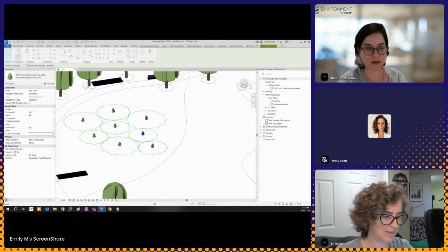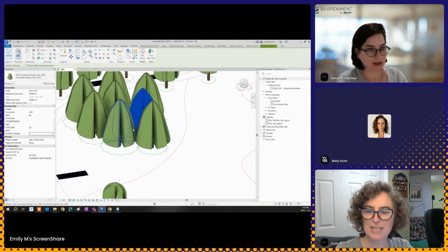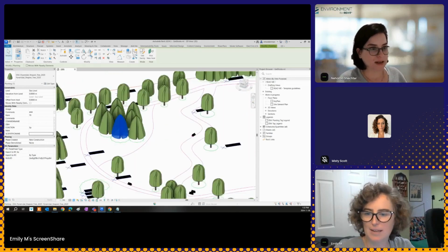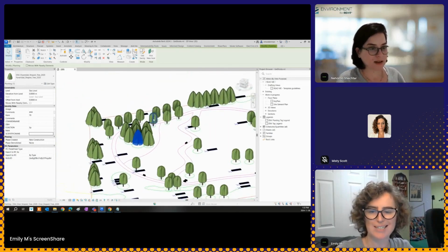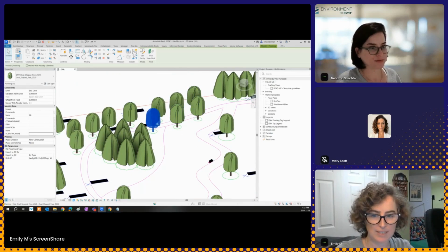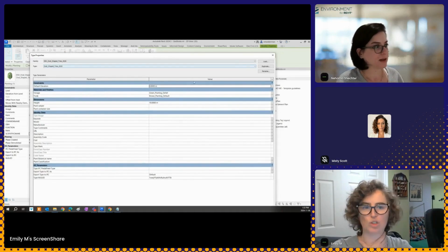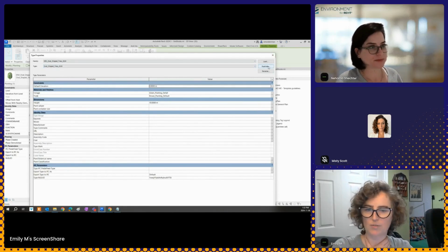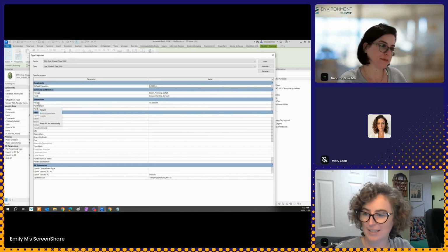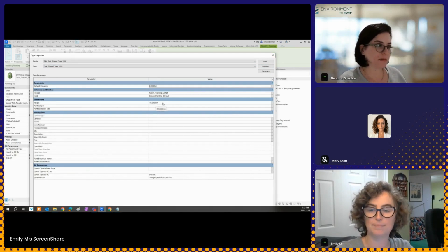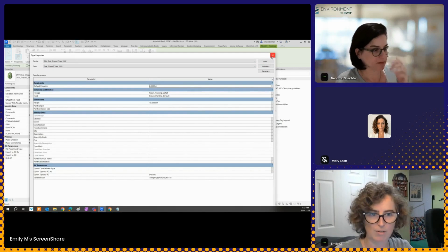Excellent. So all of these super tips, and now I'm just taking my Revit block and giving it an appropriate size, and they're all tied together. If I need obviously different sizes for different blocks, that's on the Revit side of things now. So you're going in, duplicating or swapping it out for other trees that you may have already made. I only have one oval shaped tree, so I can duplicate this for the various sizes that I need. In this case, my height and my size is a type parameter. So that's why they're all moving as one.